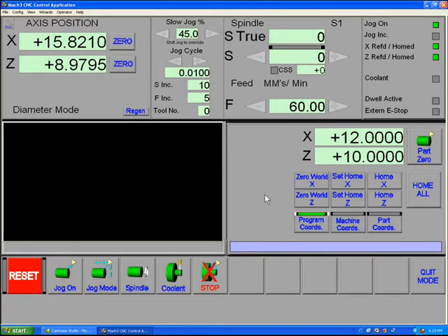This screen is meant for setting up and adjusting your lathe's position to match up with your coordinate positions that are displayed here. You can see there are only 2 DROs. It is possible to add more, but it is difficult as well. If you're going to use a tool changer, it's best to use the tool screen to simply drop an extra DRO on while you debug macros that are used to drive a tool turret. But again, that's an advanced thing, and we won't get into that. At the moment, we'll assume that you're using just your standard 2-axis lathe.